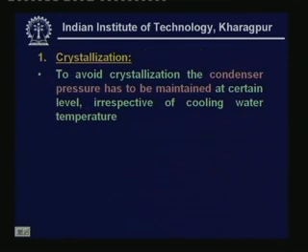Crystallization, as you know, happens as a hot strong solution is cooled. When a hot strong solution is cooled, you will find that at a particular point, if the inlet pressure is not very high, the exit condition of the solution may enter the crystallization region. Once it enters the crystallization region, solid lithium bromide crystals are formed, which you want to avoid.